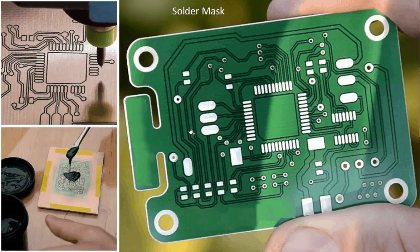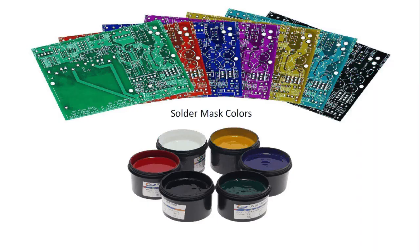Basically the solder mask layer covers all this copper layer, and only the component pads are exposed so that components can be soldered, and the rest of the copper is covered under it. This is the layer which gives the PCB its iconic green color, and these days we have various color options. At the time of ordering a PCB, we can ask our manufacturer to provide one of these.